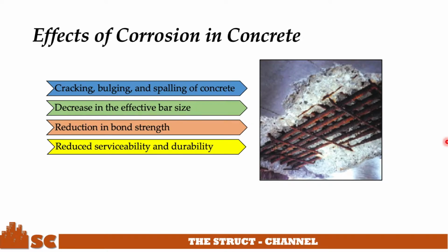However, when the embedded rebar begins to oxidize, the effective bar size decreases and the adhesion of the steel-concrete interface starts to deteriorate. Lugs and ribs of the rebar will be corroded through continuous corrosion, resulting in the dissipation of the wedging action at the contacting surfaces. In turn, at a certain critical level of corrosion in steel, the bond will be reduced significantly, causing the bar to slip from the enveloping concrete. With these undesirable effects of corrosion, it is therefore essential to develop a model of predicting the bond of corroded steel reinforcement in concrete.